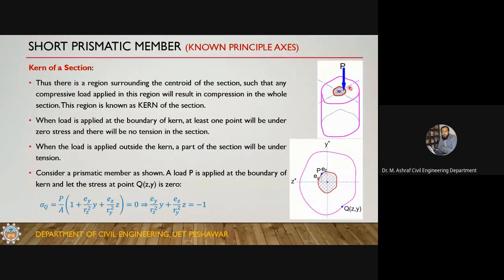If you want to place a load outside this region, what will happen? A part of this section will be under tension, which is not desirable. So the definition of the kern region is important, the determination of the kern region is important. You should know this is the kern region, and you want to place the resultant of the load within that region.